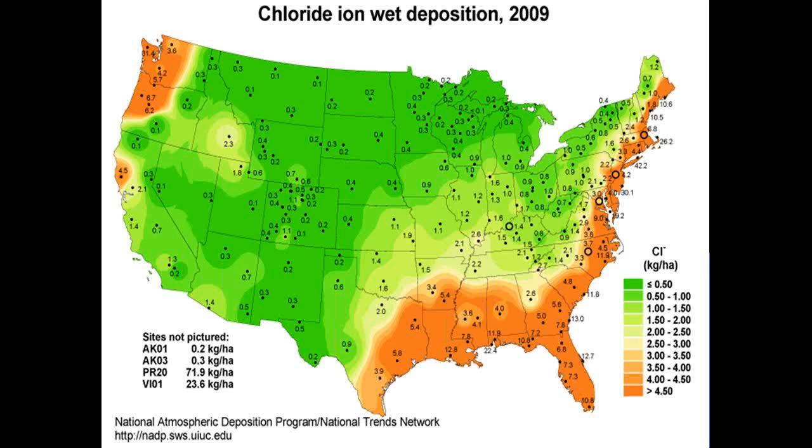That's the amount of chloride just naturally deposited out of the air in 1 year. So again, we look at southern Illinois, right where the Ohio River meets the Mississippi River. See, we got 260 micrograms per year, and what we're looking at for allowable levels is more down in the neighborhood of 3 to 5 to 7. So though the rainwater washes off a lot of it, there's also a lot available.